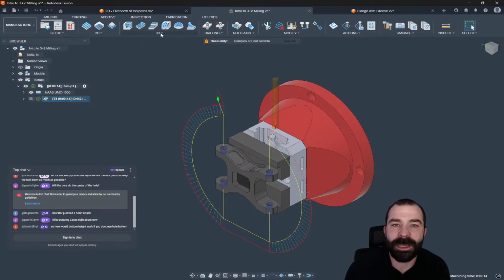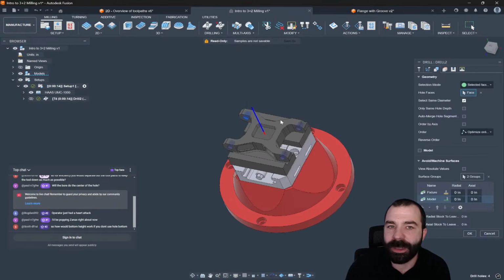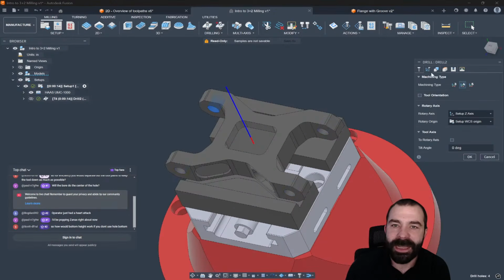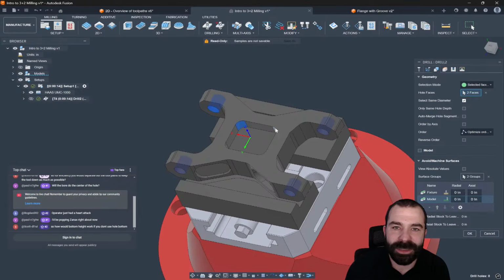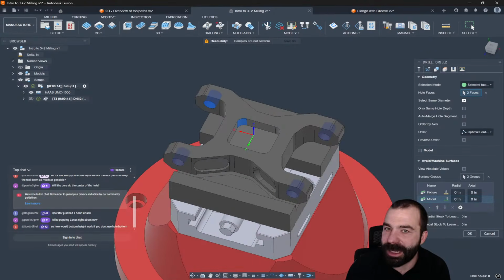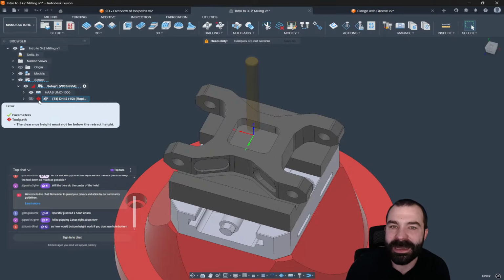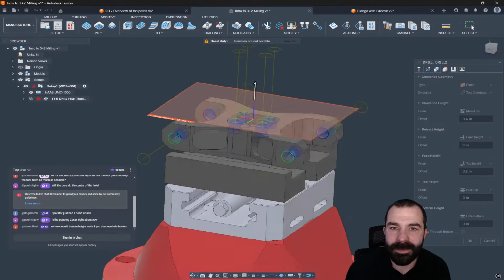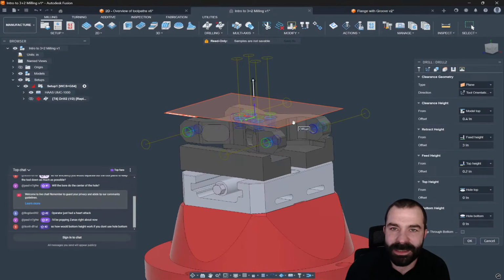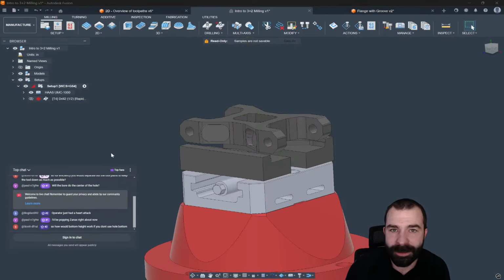So let's look at now a 5-axis scenario, right? So what I'm going to do is go back in and add, and again, I do this with drilling because drilling calculates very easy. However, it makes for quite interesting results because again, we're going to go 5-axis now. And with that, I'm going to drill basically the corners here, if it'll let me. So as you guys are going to see now, it will not allow me to do that because the clearance height must not be below the retract height. So when we go back and look at our heights tab, as you're noticing, our clearance height is causing the problem. So we're going to go ahead and pull that up a little bit. We're actually going to have to pull that up a lot.